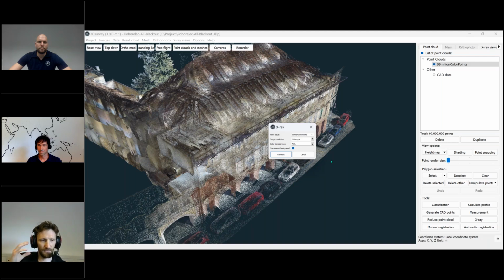Keep in mind, the greater the transparency, the lesser the impact of a single pixel, of a single point. So if you lower the transparency, each point will have greater density and it will make lines thicker and brighter. For most cases, we can keep that at about 70, which is default. And if I click generate here, this will take about 5 to 10 minutes on this computer. So I will skip this and just show you what I've already done.